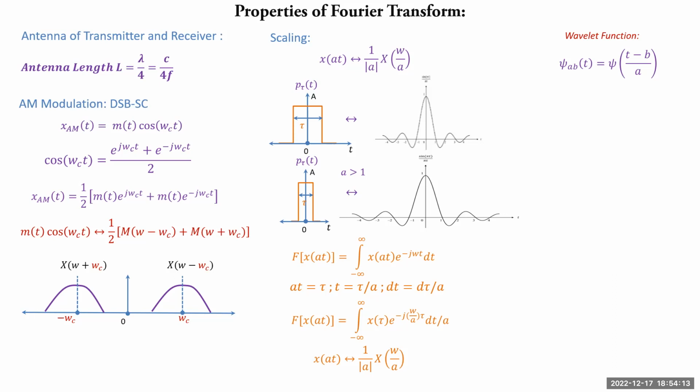So basically it provides a short wave which is called wavelet, which can be shifted on time axis to span the entire signal, and the signal can be observed with a different resolution with the help of parameter a, and that's why it allows simultaneous time and frequency resolution in a wavelet transform, and it offers huge amount of applications, especially analyzing transient signals.